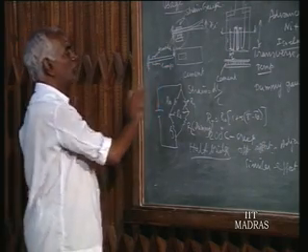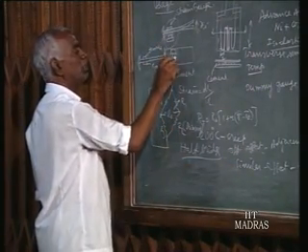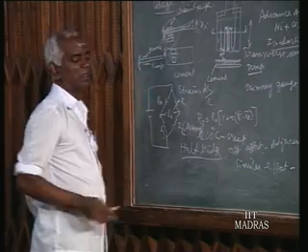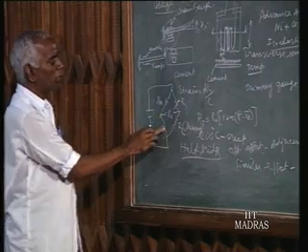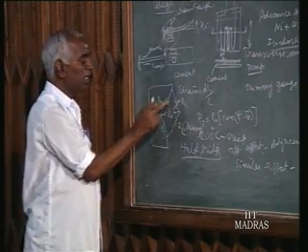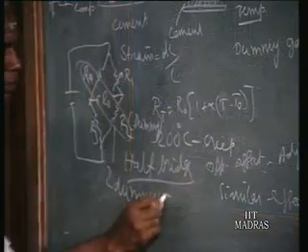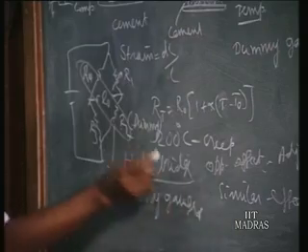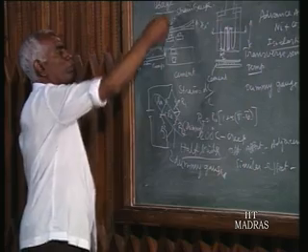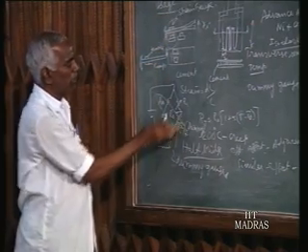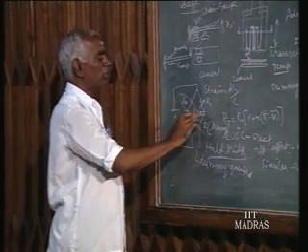Whereas if you are using the similar effect, that is putting two strain gauges at the top of the cantilever itself, then both the strain gauges will be picking up a similar strain, tensile strain. Then we are putting the opposite arms. If you put opposite arms, temperature effect also gets added up. In that case, you should go for two dummy gauges. You put one more dummy gauge, same material dummy gauge, one behind the other, because all the four strain gauges will be simultaneously affected by this temperature, and you will find that effect will be 0.